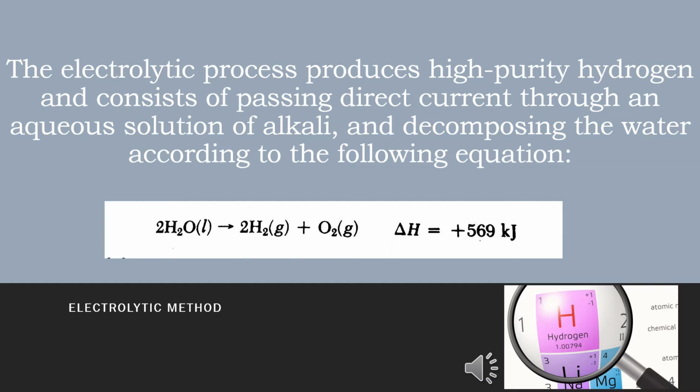The nickel plating of the anode reduces the oxygen overvoltage. Most types of cell produce about 56 liters of hydrogen and half as much oxygen per megajoule. The gas is about 99.7% pure and is suitable even for hydrogenating edible oils.